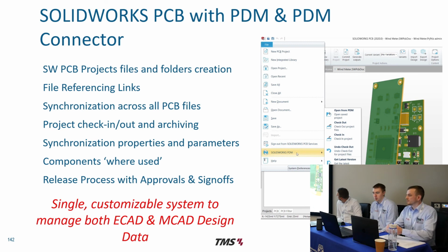Now, with SOLIDWORKS 2020, we now have the functionality of working with PCB and PDM internally within the PCB application. We no longer need to use Windows File Explorer in order to do this. We also now have the ability to create some reference projects, so it has all those file references in there before we even start anything. And because we're using PDM, we can follow all those commands that you're used to, the where used, the release process and approvals, that sort of idea.